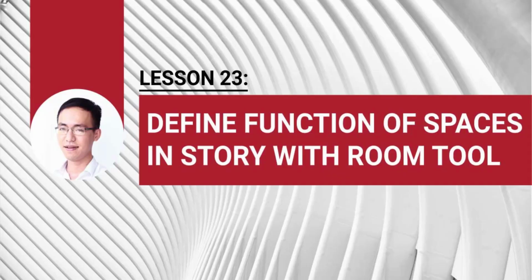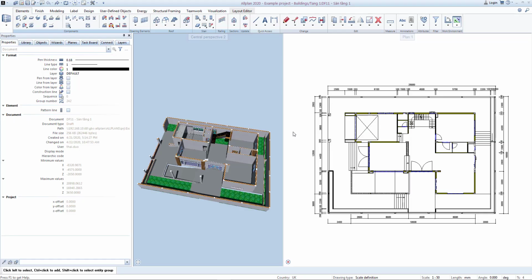In the previous video, we have created the slabs for the first floor. The walls, columns, slabs, doors, windows, and the stairs have been modelled. Today, we will get acquainted with an interesting feature, the Room Dividing Function Tool. With this tool, we will get the names of function spaces and their dimensions.